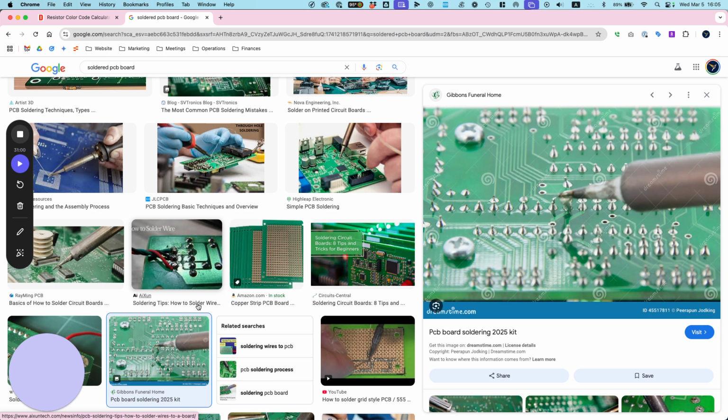So it's spring loaded, and then this tip right here you place right against the part that you want to remove, and then you press this button here, and it's going to pop out, and it's going to suck it out here, and then you have to reload it again. And when you reload it, it's going to dispel any solder that is sucked out, and it's ready to go. So it has like a ballpoint tip.